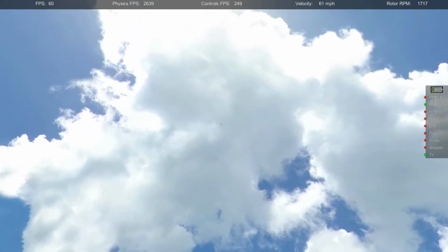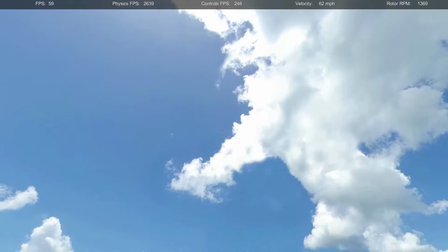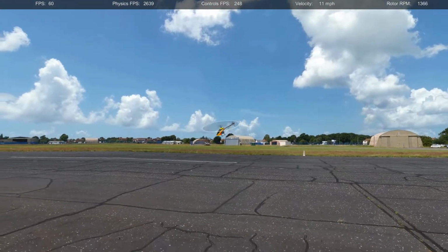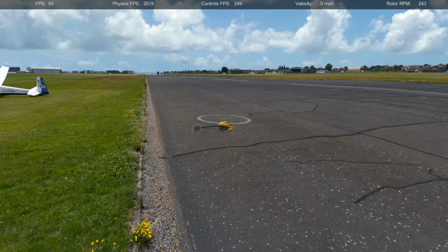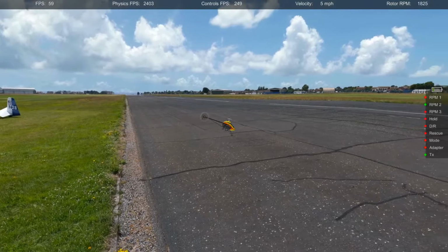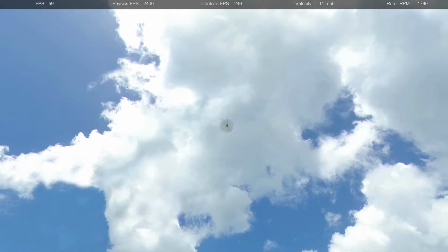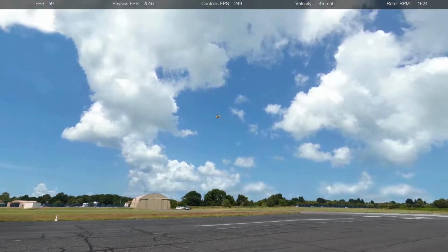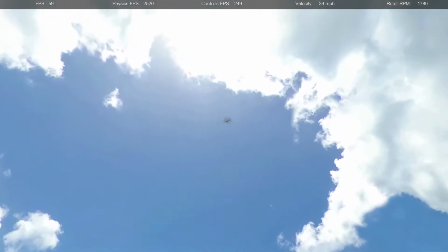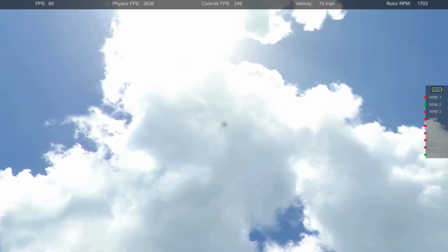So Prandtl still thinks about this problem. He wasn't trying to solve the bird problem or anything, but he came up with a new solution in 1933. He came up with an alternate solution, and it's that curve C up there that tapers off, the load tapers off to nothing at the wingtip. And if you think about this, the load goes to zero, so all of a sudden, feathers sticking straight out at the tip makes perfect sense. Now, the new constraint on this wing is what he called integrated bending moment.